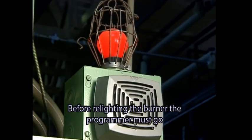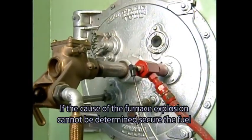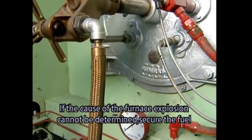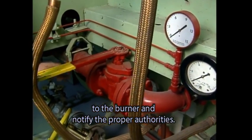Before relighting the burner, the programmer must go through the purge cycle. If the cause of the furnace explosion cannot be determined, secure the fuel to the burner and notify the proper authorities.